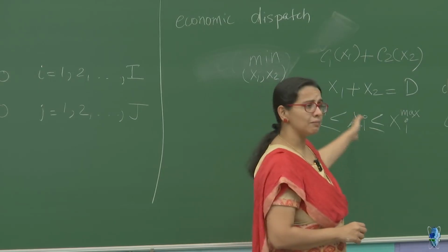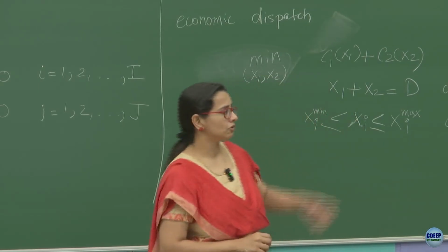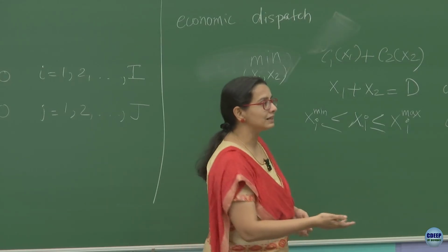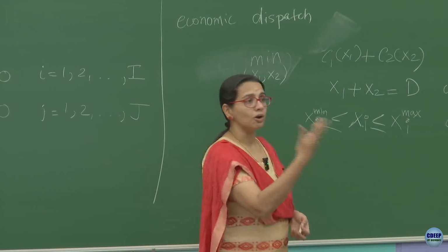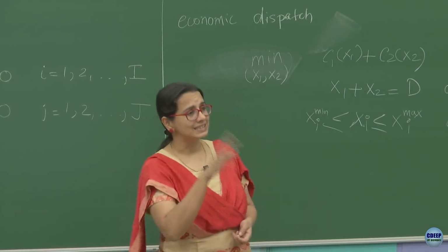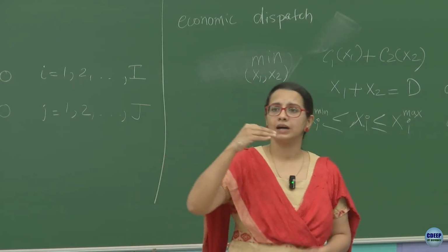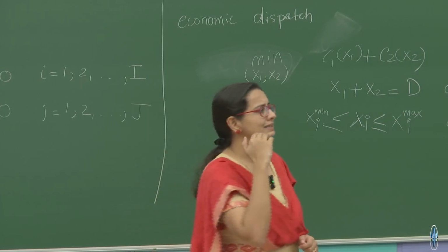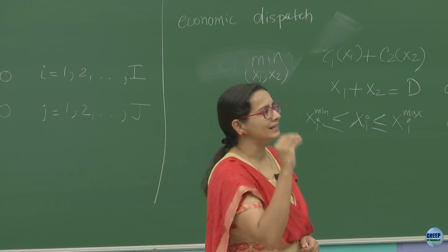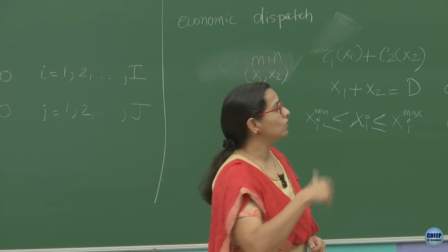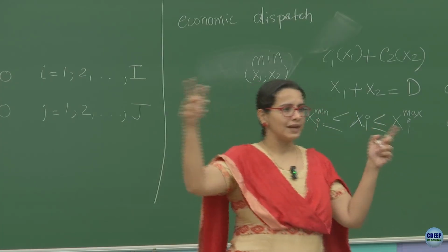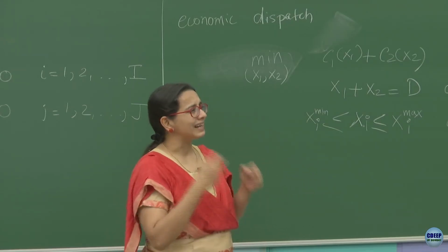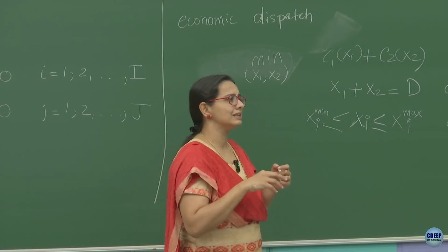You're eventually framing a math problem and you're trying to minimize cost. It should not ask you to produce minus 100. So 0 is an obvious minimum limit, but certain generators may have another technical minimum outside of 0. It may need a certain minimum load to guarantee economic feasibility. For example, for a 500 megawatt generator, below 100 megawatts it's actually very, very energy inefficient.